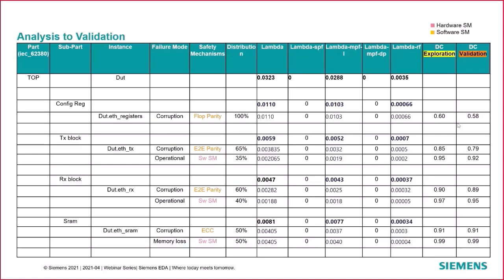One of the factors is whether we were able to perform the fault injection for both flavors of the fault, stuck at 1 and stuck at 0. And if our input is not sufficient and we are only able to perform fault injection on one, then we have some gap in the fault injection with respect to the fault stimulus. So this could be one of those things.